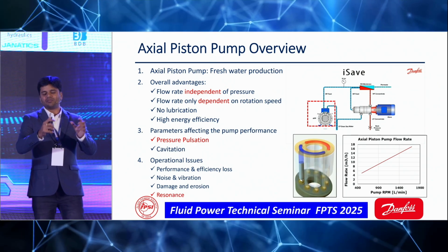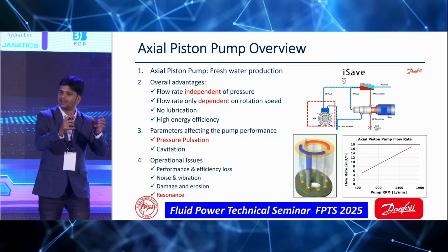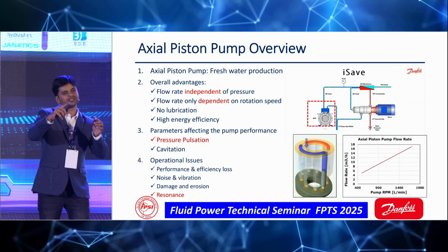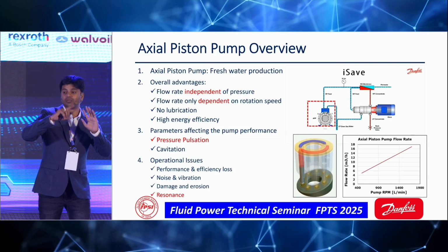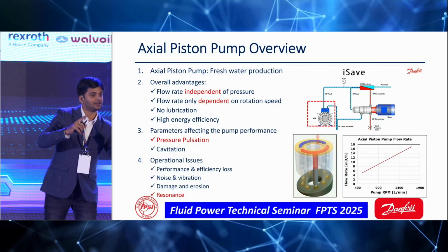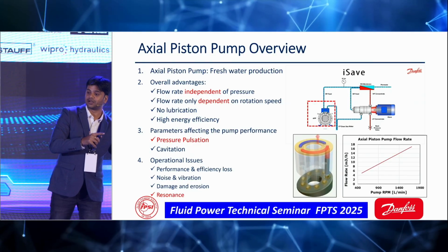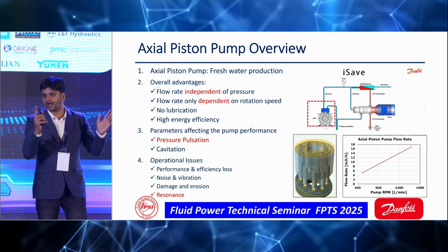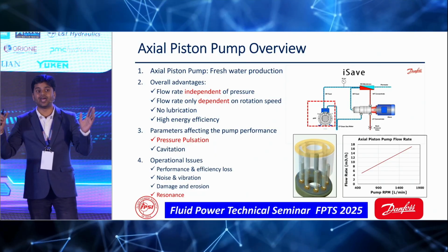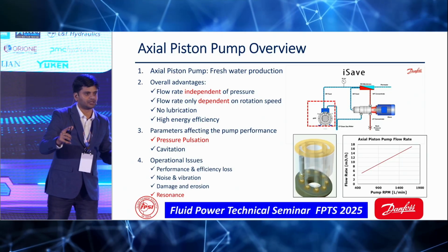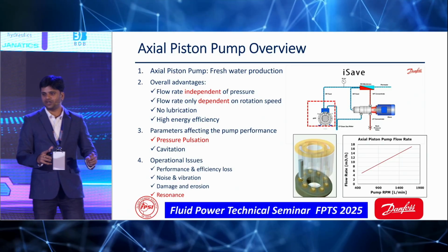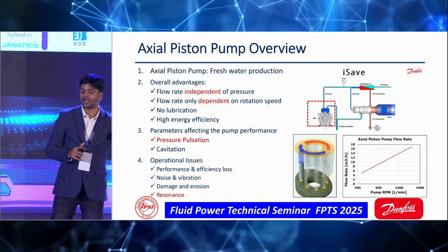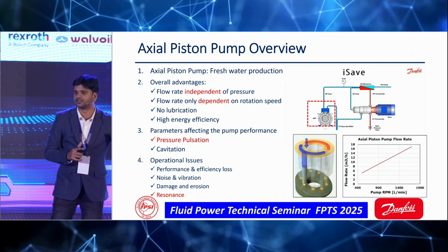Let's say that one pump has 4 pistons on the discharge side, so you will have 4 pulsations. And 4 pulsations times 1500 is the number of pulsations it produces in a single minute. Imagine this kind of pump running 365 days a year throughout a decade, 10 years, and you can imagine the damage it causes to the hydraulic system. This is exactly why it is important to mitigate these pulsations and meet certain compliances.